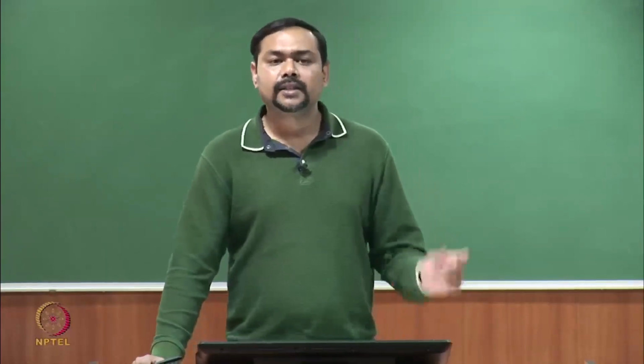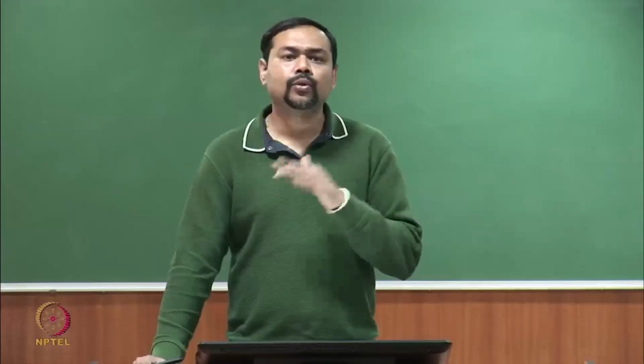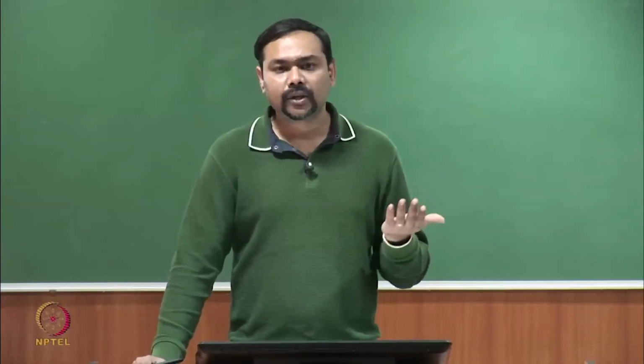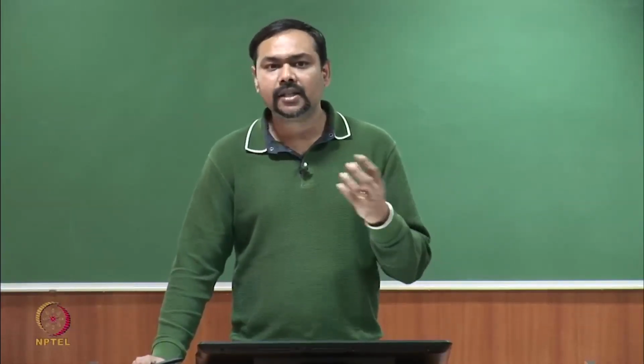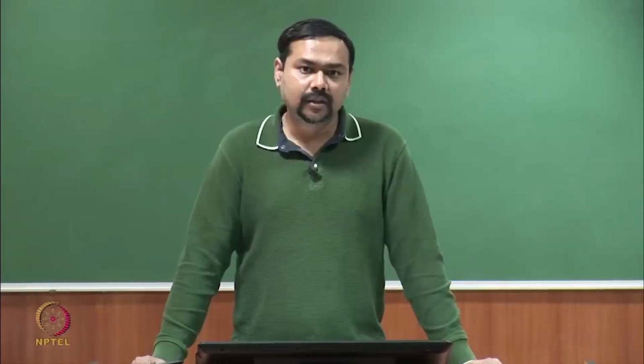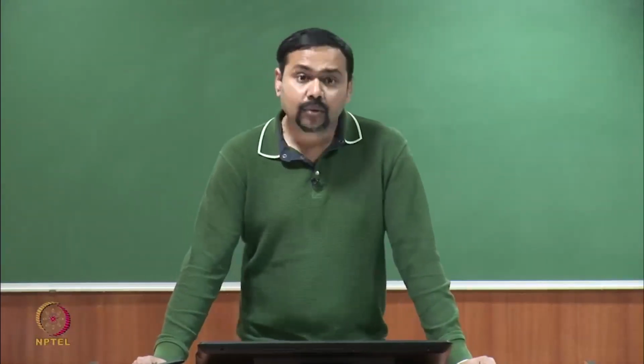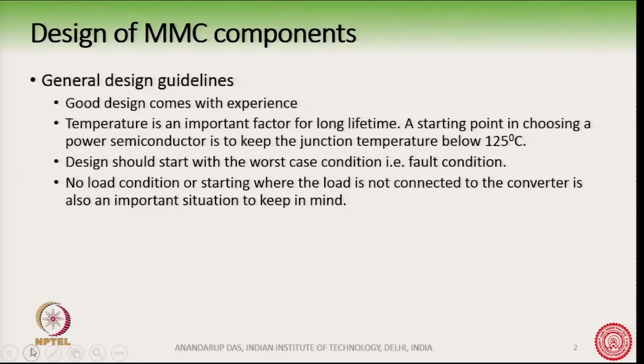Often we do not get the same value of efficiency from no load to full load. So we then choose that the efficiency should be highest near the rated operation of the converter. No load condition is also something to be kept in mind, because in a no load condition the load has been thrown off the converter. How the converter will behave in the absence of a load is an important factor to be kept in mind.